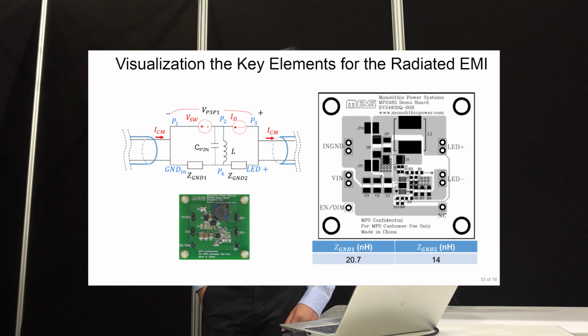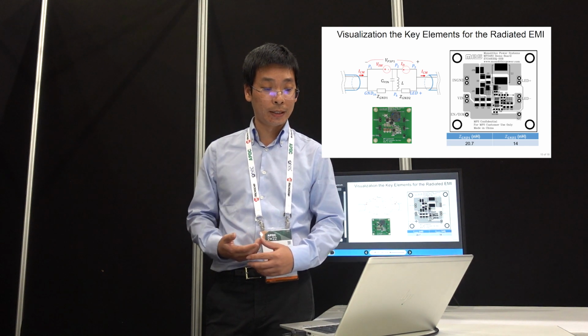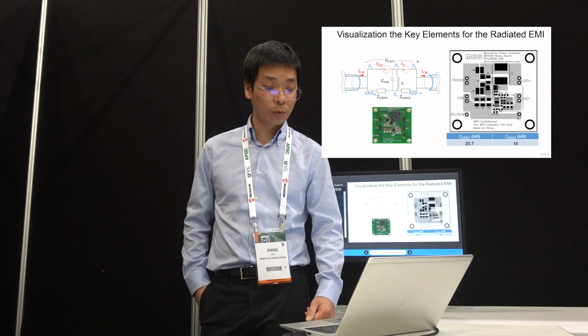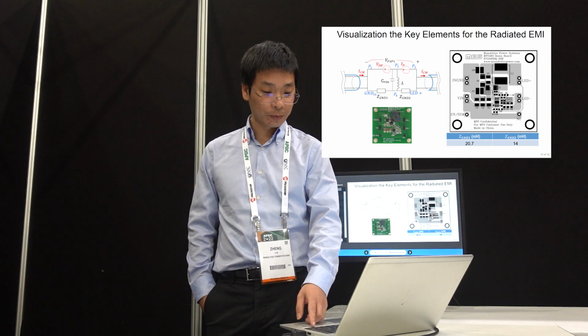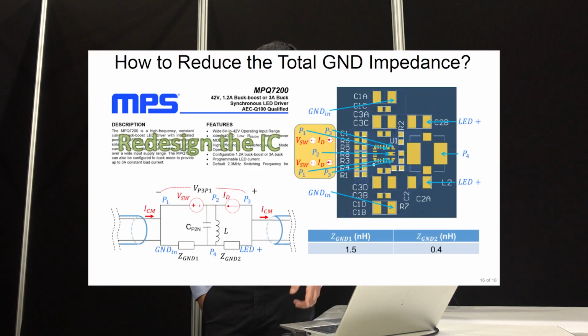So I want to give you a visual idea of how much this loop component is. This is actually a typical, pretty well-known non-synchronous DC-DC layout. Basically you have to have this space to accommodate the controller and your FETs, and that distance is creating the parasitic inductance, and we measured about 21 nanohenry for the ZGND1 and about 14 nanohenry for the ZGND2. It's not too much, right? But this is what you need to generate your radiated EMI.